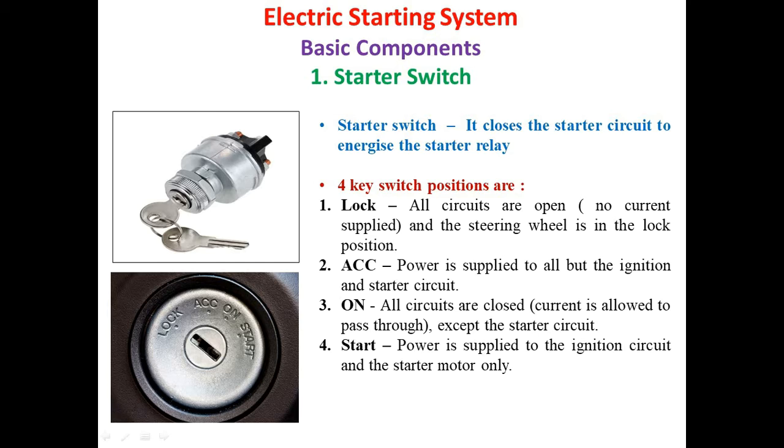And the last position is the start position. Now in this position, when the key is operated from the on position to the start position, current will be supplied to both the starting and ignition systems, and all the rest of the accessories will stop functioning as their circuits are open.